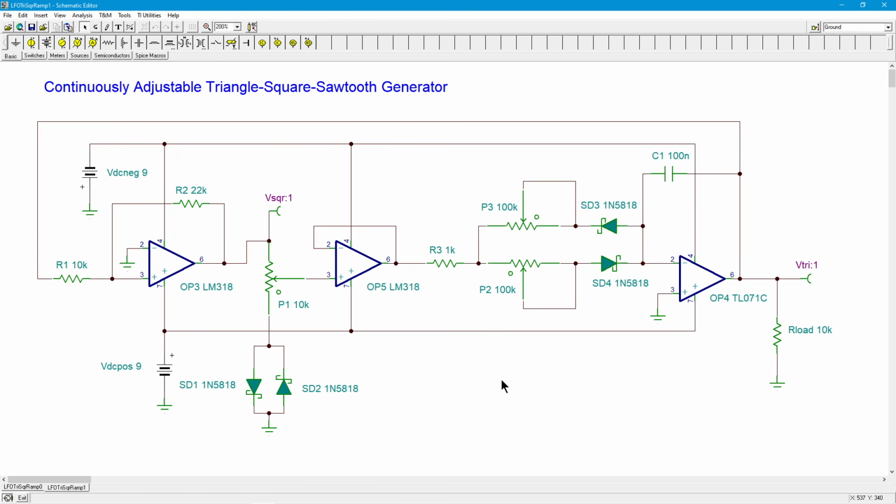Well, two reasons. A, they're fast, which is good, but a major reason is because the voltage drop across them in forward bias is smaller. So instead of getting 0.7, maybe we're only going to get 0.3 or 0.4, and that's going to improve, as you'll see momentarily, the range and accuracy of this particular circuit, right? But still, we're just going to think of these as kind of like switches, allowing current in this direction here, allowing current in the direction like this for the upper path, right?